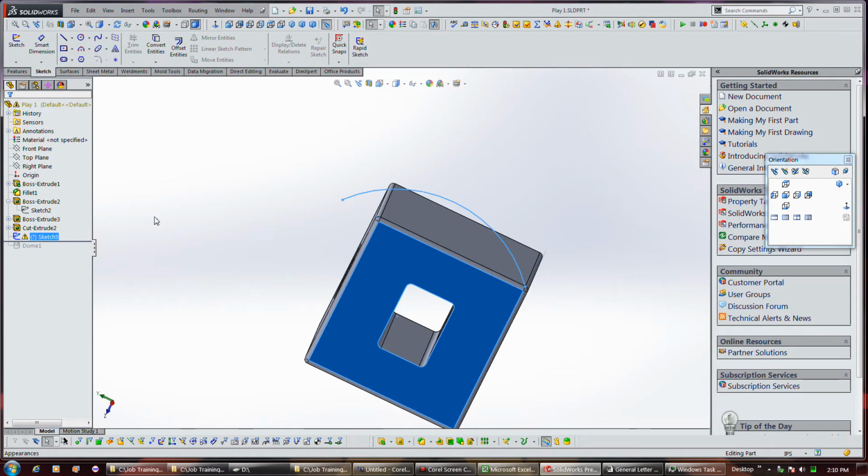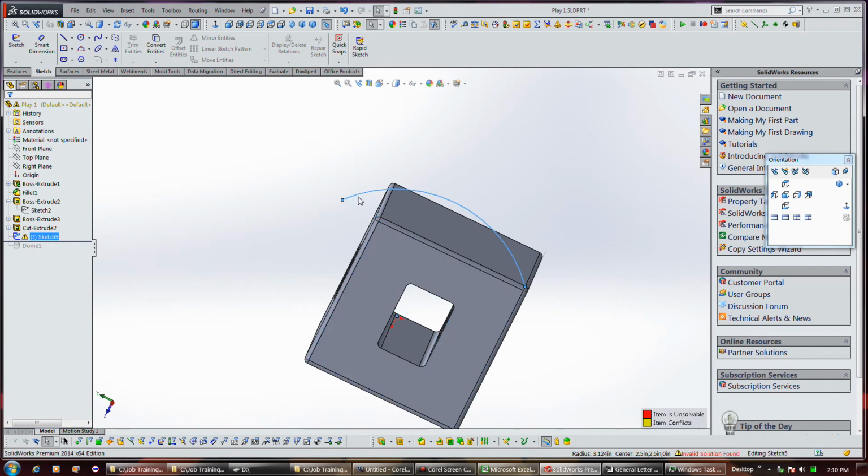And I think I know what the warnings are. And you can double click on a sketch, by the way, and generally get into it. But yeah, I understand what the warning is. It's to put a coincidence, like an origin point or something like that, on that face.